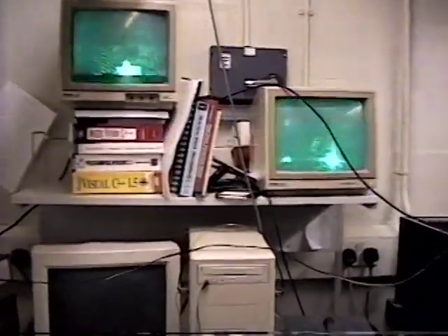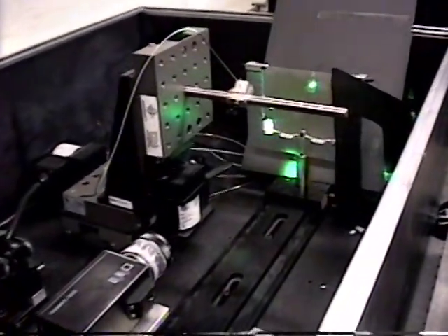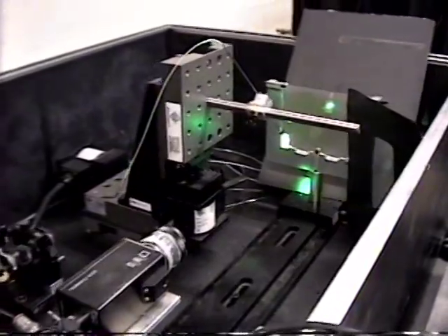Okay, I developed the 3 holograms, and now I've viewed them. However, the particle brightness is somewhat limited in these holograms. This is the one for the single line, not planar, just single line, I believe. Even then, the brightness is somewhat sketchy, but it's enough. This is bright enough to give us fringes, and the fringe spacing seems to be pretty reasonable.